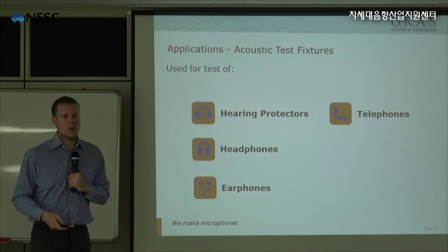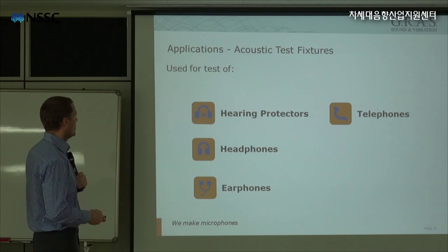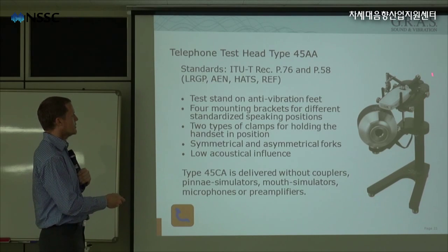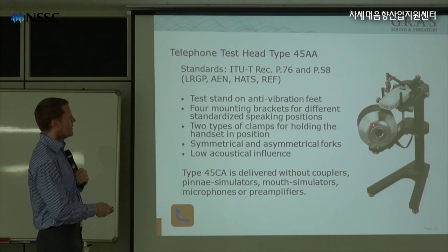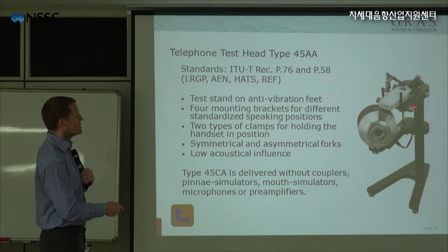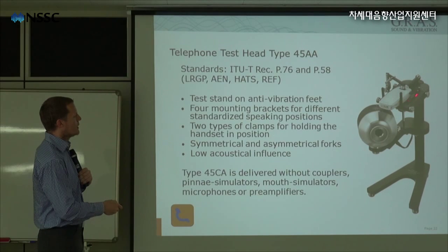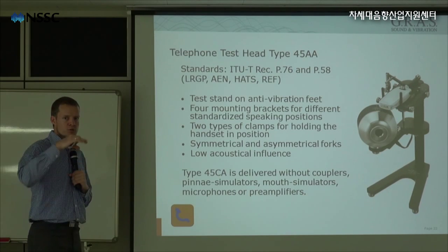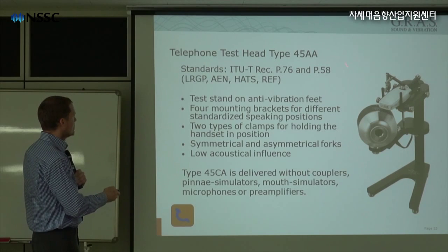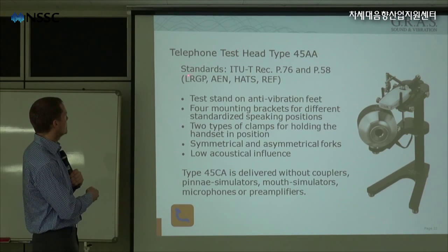If we go into some of the acoustic test fixtures that we have, I would like to show you the telephone test fixture. It looks like this. You have a mouth, and then you have a 711 coupler placed in the jig up here. So underneath the telephone you have the coupler, and it's very carefully positioned here in a position suited for telephone testing. So this test jig is standardized according to ITU